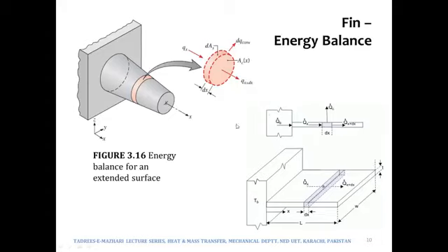Now, starting with the fin energy balance, we will see in a bit where this fin energy balance will lead us. Let me tell you over here what we are going to do: we are going to find out the temperature distribution in a fin. Means if this is the fin, how will temperature vary all along the length of the fin. So we are trying to find out temperature as a function of x in case of a fin, and heat transfer rate we will see in the course of this PowerPoint presentation.